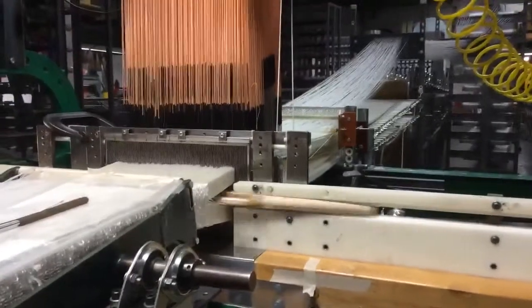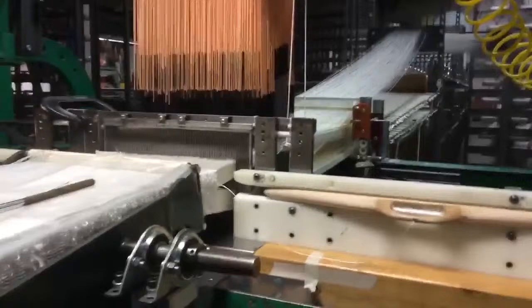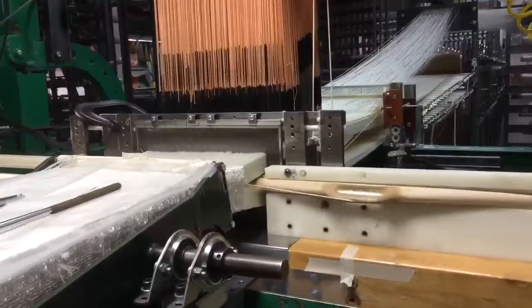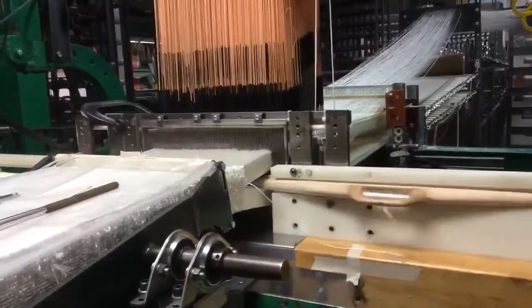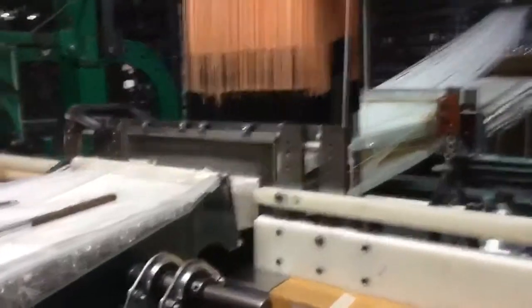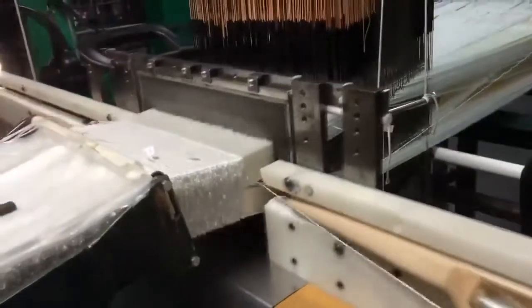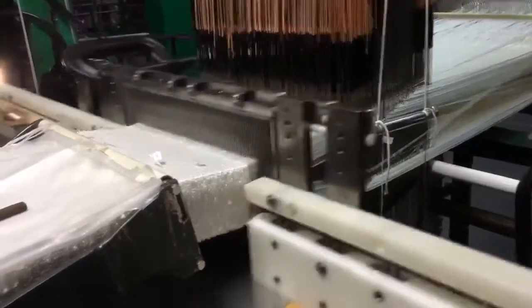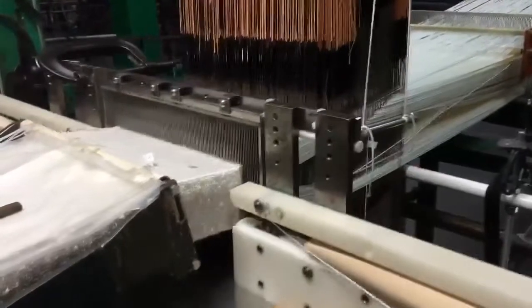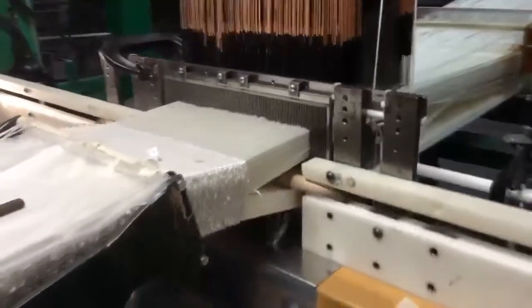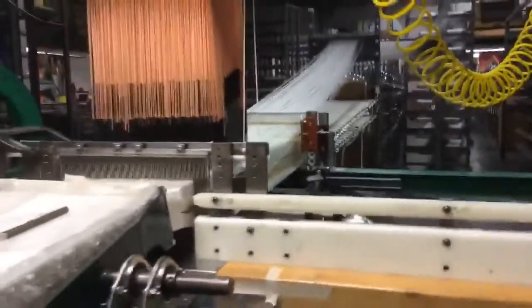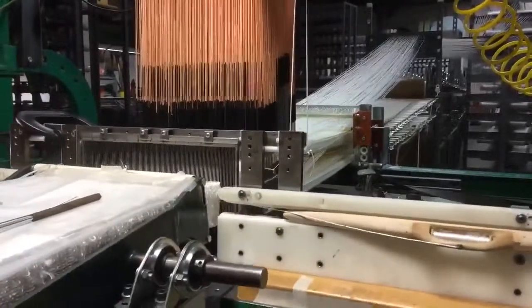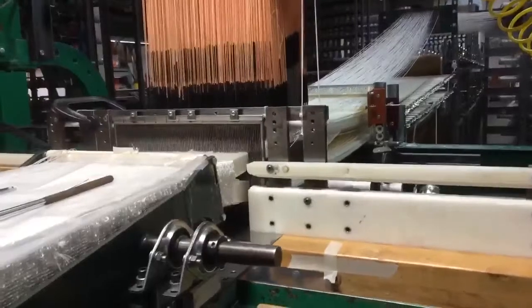Okay, here we go. So this is the loom in action. I mentioned you see the shuttle going back and forth here that contains the fill yarn. It has to go back and forth for each one of the layers in this material. In the Z direction, it's built up about 50 layers, and the shuttle has to go through each one of those 50 layers before the loom can advance one step in the X or warp direction. So it's a very slow process to weave this. A 13-inch long part takes on the order of a day of continuous weaving.